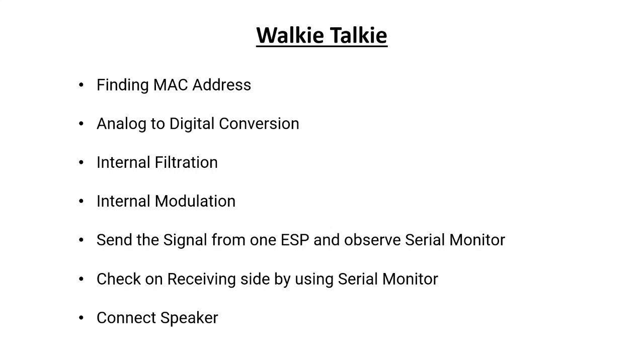And then, once you are clear that it is working, you can connect it to the speaker. Of course, this will need some additional filtration. Before connecting to the speaker, you have to do some filtration, amplification, and power amplification. All this is done in the ESP. You can say that this all will be done in software, using code, and you just need a microphone, a speaker, a power amplifier, and an ESP.